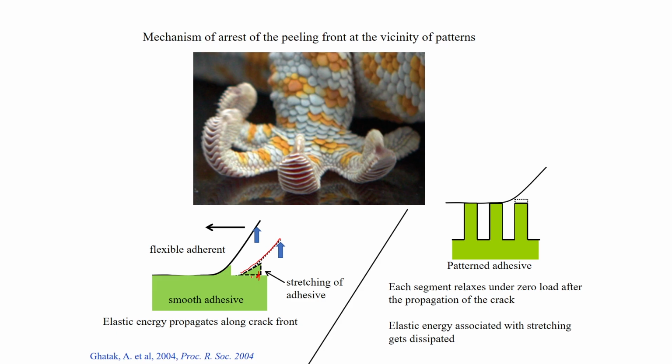this amount of the film. So, there is some amount of elastic energy that gets stored, and as this particular plate is lifted further, this contact line moves. If the contact line moves, this portion of the film goes down, but this portion of the film now has to get stretched. So, the stretched portion also propagates, and it stores some amount of elastic energy. So, this elastic energy gets propagated continuously from the right side to the left side over here, because the adhesive film is continuous. So, this elastic energy that is stored can